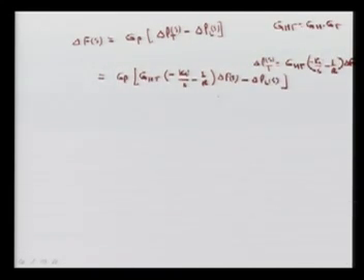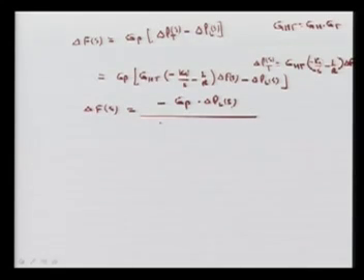So now we can simplify this. Change in F will go to that side. So I can write ΔF(s) is nothing but minus Gp times ΔPL(s) divided by 1 plus Gp into GST, multiplied by Ki over s plus 1 upon R, because the minus we have taken to this side, and when we move it here it will be added.